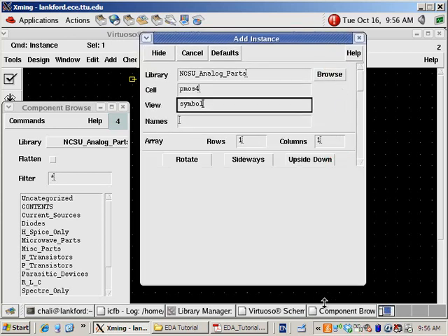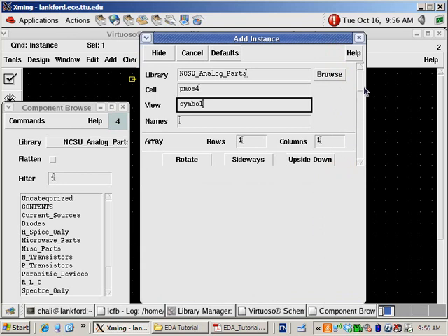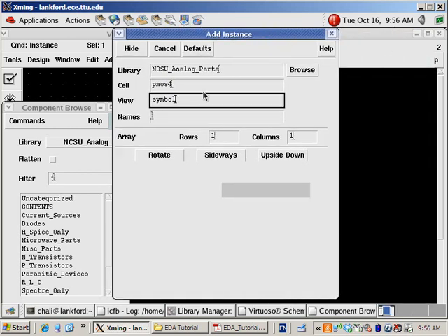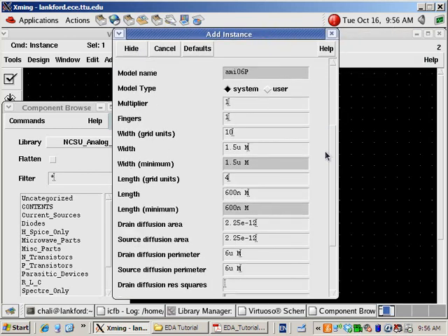After that, I have to change the property of the PMOS. It's amazing that every time I do an EDA tutorial, it works slowly. Okay, so PMOS, first for the width, I'll change it to 8 micrometer. And for the top 3 PMOS, the size is 8 times 4. So the multiplier will be 4. And the length is 2 micrometer.